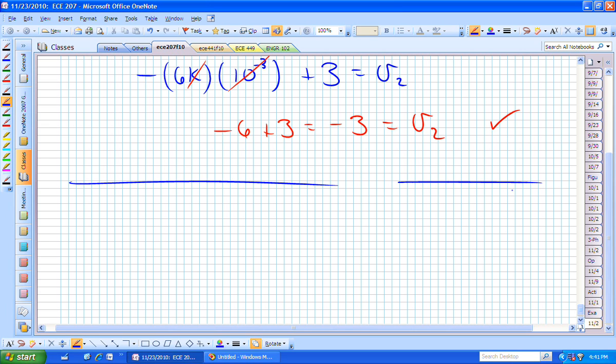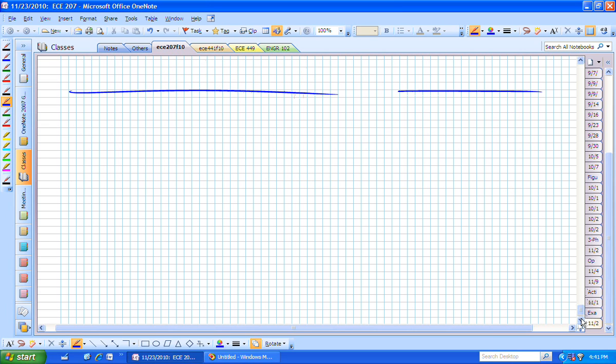But they work like a diode, which means you might put up a power supply, a resistor, and then a diode, where that diode could actually be an LED. If you get current to flow through that diode, it's going to illuminate. It's going to be bright depending on how much current you push through it. If you push too much current through it, pew, it's going to be gone. It would have been bright for an instant, but now it's no longer going to work.